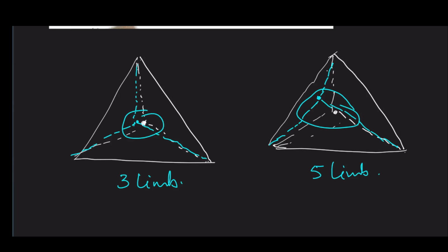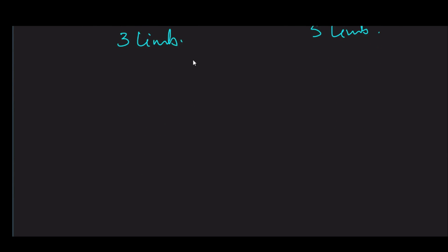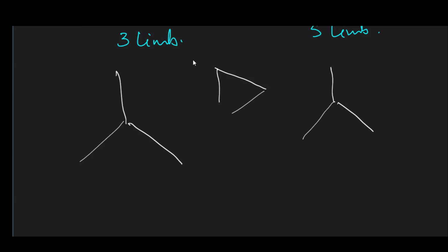Shell type transformer, due to its construction, provides extra iron path for the flux to circulate, like the third harmonic flux. So that is a problematic thing. In order to circumvent this issue, we use a delta connected tertiary winding. What is that tertiary winding? Suppose you have one star connected primary and another star connected secondary. Now what you can do is just introduce a tertiary winding in between.